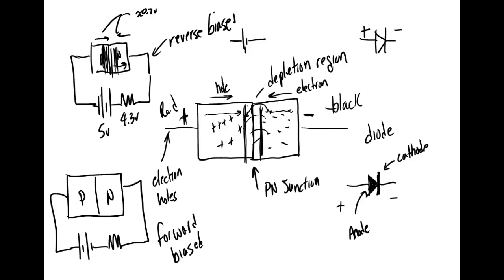So this symbol is used for two types of diodes. This is used for a diode we refer to as a rectifier. And it's also used for a diode we call a small signal diode. So a rectifier diode is usually low frequency, because the predominant frequency, power frequencies all over the world, you've got one or two frequencies being produced as far as transmission.